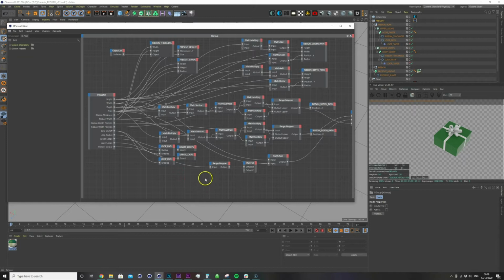So to do that, we introduce a new node, Xpresso logic condition. And again, this is going to control our switch. But the fortunate thing about condition nodes is that you can set it to integer, and integers only read whole numbers. So 0.25 is 1, 0.5 is 1, 0.75 is 1, 0.99 is 1, which is absolutely perfect for what we need. We'll add 4 of those. Yep, so for our condition node, we start with 0, and then 1, and then 2, and then 3.